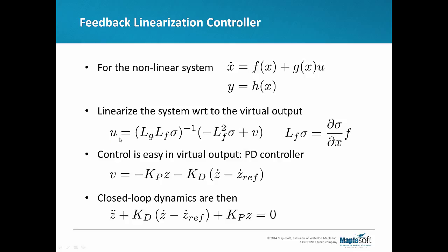And so what we want to do is now build up this linearizing controller in Maple. And this is the outer loop controller. There's an inner loop controller that works as a PD controller. And this is going to get us our desired closed loop dynamics that tells us that our distance to the circle is going to disappear. And we're going to have some desired velocity around the circle. Okay, so let's take a hop into MapleSim and see what we're talking about here.